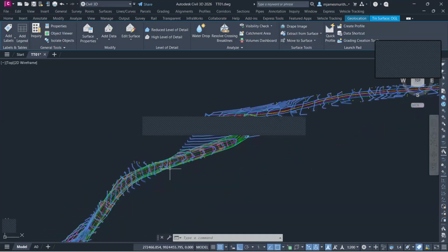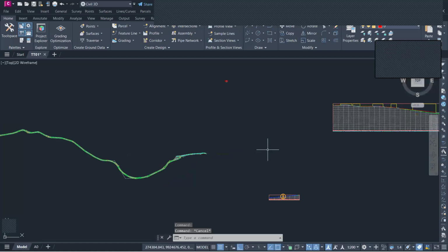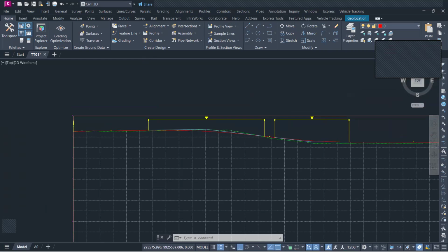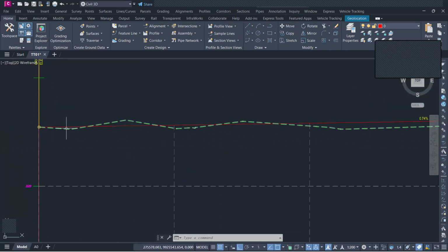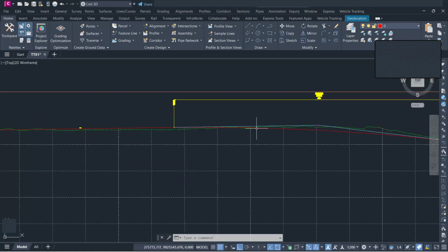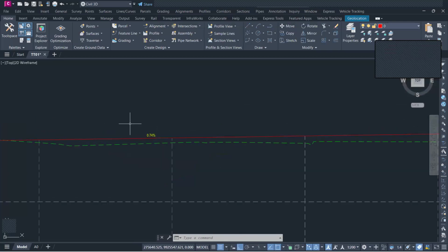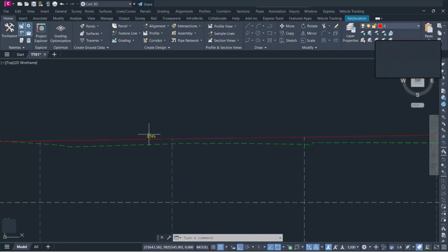Great. So if you look at, for example, these design projects, we have what we call a profile. And we say that the road profile basically gives us the OGL. And once you have the OGL, you will have what we call the formation level of your road. So with this formation level, or the vertical profile, you decide the amount of gradient that you need. These are the major design controls: the gradient of the road.